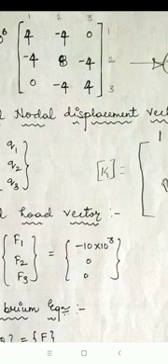And in the place of column 1 and row 3, I have written 0, because in both stiffness matrices K1 and K2, we won't find a value at column 1, row 3. That's why I take that value as 0. Similarly, in column 3 and row 1, there also I have written 0. In this way, we have to find the global stiffness matrix. Next, step number 4, the nodal displacement vector, that is q equal to q1, q2, q3. These all three values we have to find now.